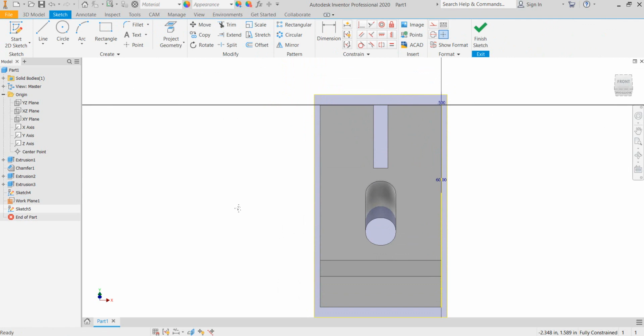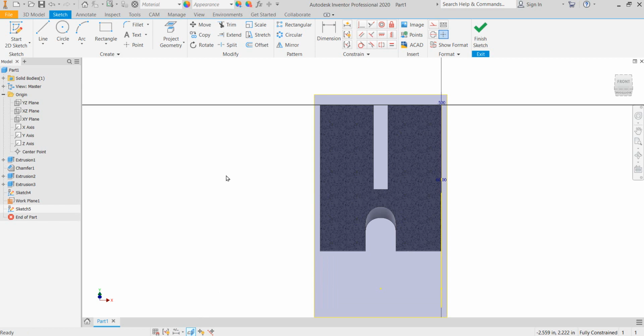And I'm going to slice my graphics. You can go F7. And let's see. Now we're going to do a line, and I want to snap it on the outside edge, but watch out that you don't grab that midpoint snap. Okay, so I'm going to anchor there, come down into here, and then come back up to here.